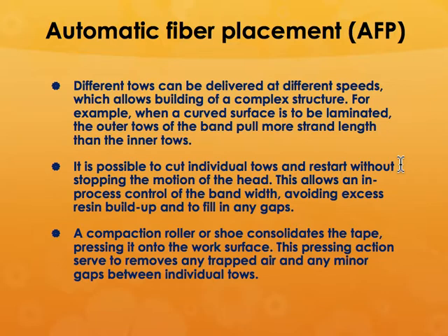You can have multiple heads, and you can have different kinds of tows delivered at different speeds, which allows for the building of a very complex structure. So if you have a curved surface, the outer tows of the band will pull more strand length than the inner tows. So you can have individual tows and restart without stopping the motion of the head. Which means that your process can be automated and you can make very, very large structures.